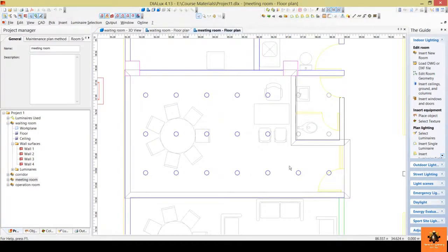And here in our case, if we count the number of luminaires, we will find here we have 1, 2, 3, 4, 5 times 3. So those are 15 luminaires, and we have here 2 other luminaires. So the total number of luminaires for this room is 17 luminaires. And if we get 25% of the 17 luminaires, they will be approximately about 4 luminaires.